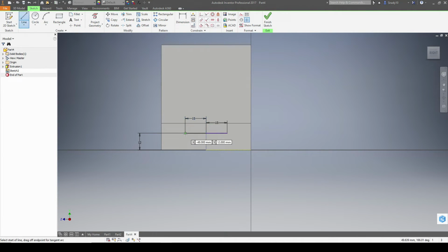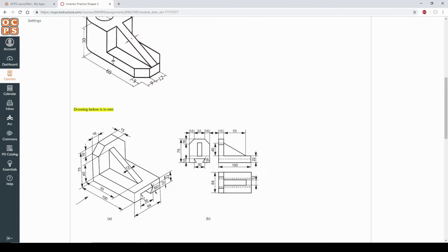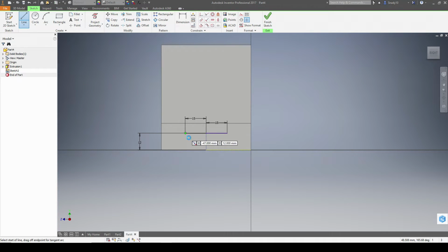So I'm going to make a line. This line right here that goes down. And it tells you that the angle of this line is at 60 degrees. Well, on this side, when I make the line, I'm not going to actually give it a measurement. I'm going to hit the tab key and go over here and type 60. Then I'm going to hit tab again. This allows me to move my angle to 60 degrees and click on that point. I'm going to do the same thing on this side, except I'm going in the opposite direction with my degrees.